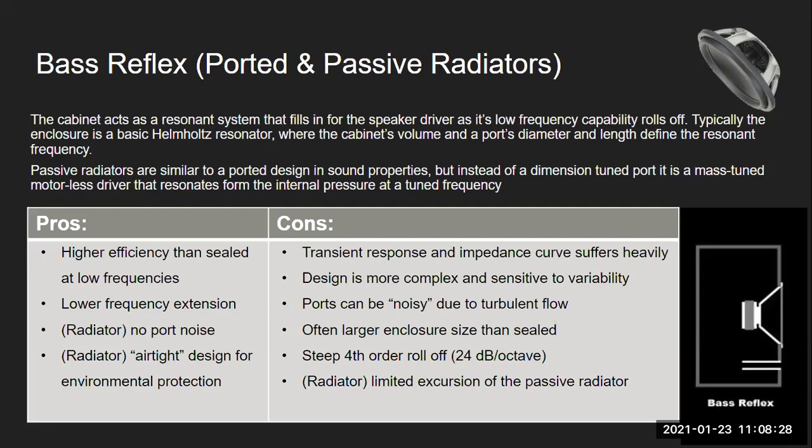So you can tune this passive radiator just by adding weight to it, and then that acts as sort of a port that resonates with whatever the volume is, and it gets excited by the active driver, and so then it starts taking over as the active driver isn't able to keep up.